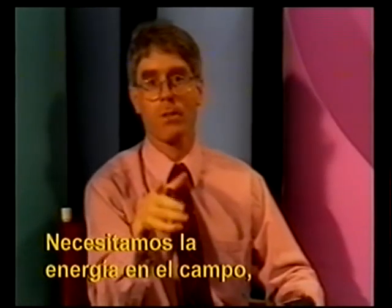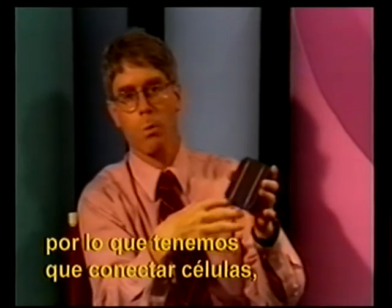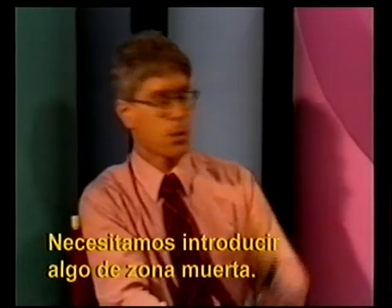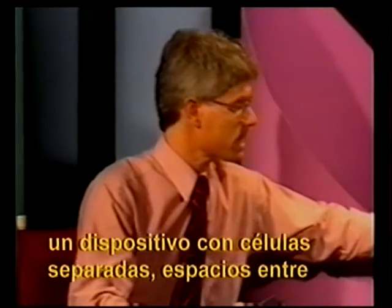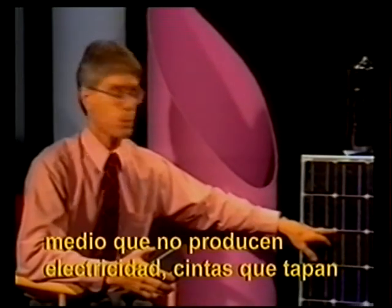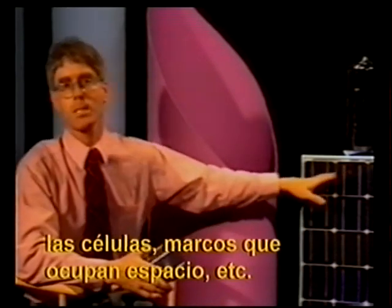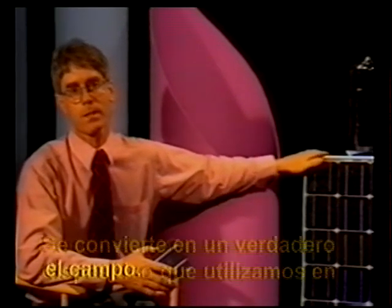We need power in the field. So what we need to do is connect cells together, interconnect them with wires, space them out. We need to introduce some dead area. So when we finally create a finished module, we've got a device that has cells that are separated in between, spaces that aren't producing electricity, ribbons that are covering up the cells, frames that are taking up space, and so on. This becomes a real device that we use in the field.